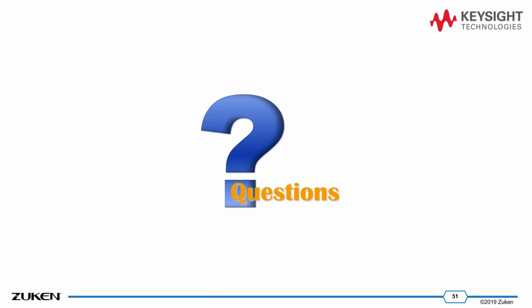Okay, depends whether we're talking about EM simulation. EM simulation takes much more time than the system simulation part. But actually, that's a really good point, because this is one of the things that IBIS AMI and an enhanced channel simulation for DDR gives you over something like standard transient SPICE. Standard transient SPICE tends to take quite a long time. We tend to want to simulate hundreds of bits or maybe a low number of thousands of bits with transient SPICE.